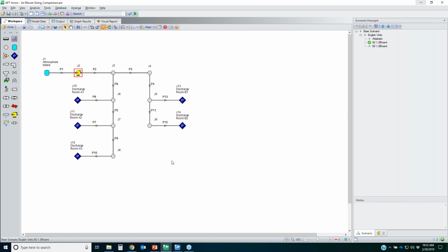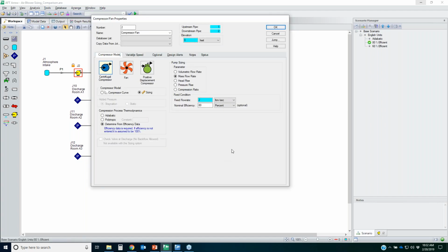Now, the reason for that is because if you have a volumetric quantity, standard cubic feet per minute, or perhaps normal cubic meters per hour, those volumetric flow rates, when you have the words standard or normal in front of them, it ties that volumetric parameter to a specific density of a gas at standard temperature and pressure conditions, or normal temperature and pressure conditions.